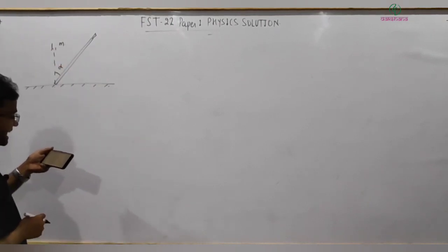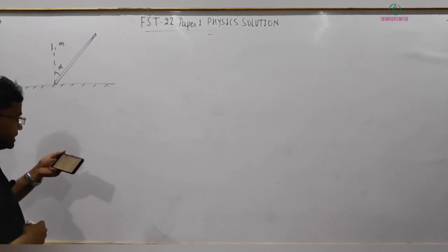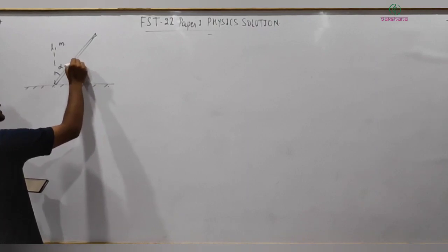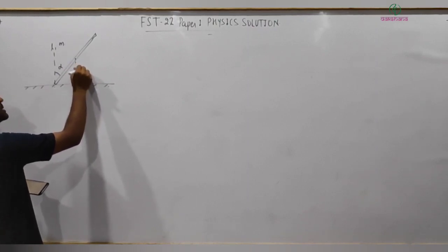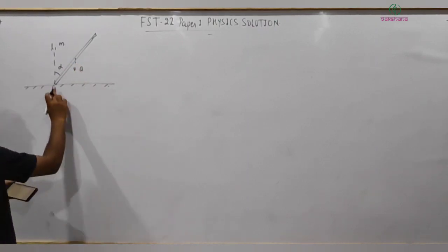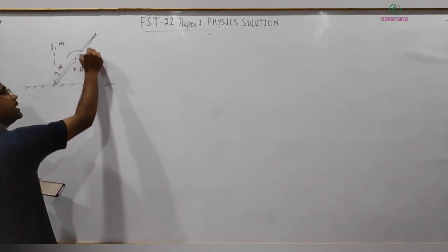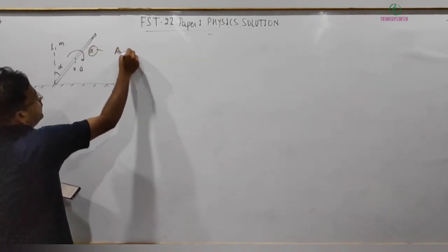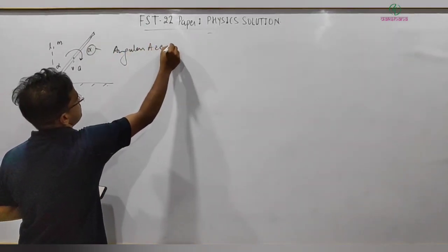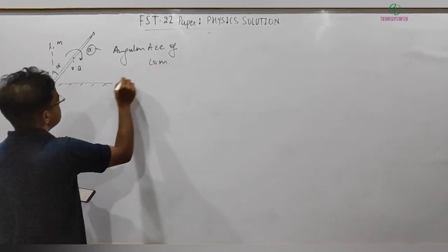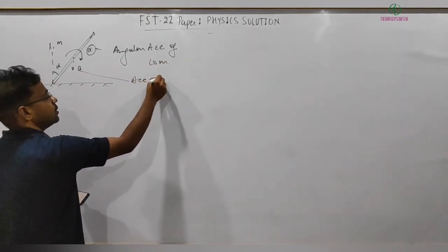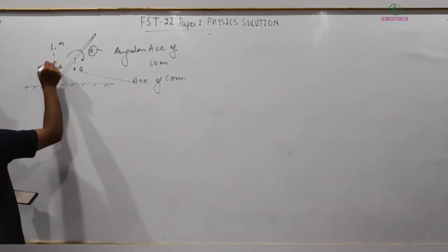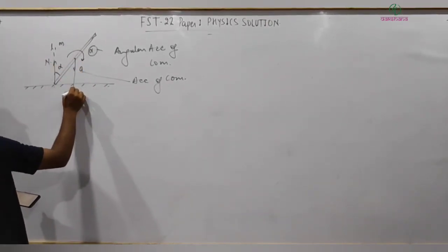The rod makes an inelastic impact with the smooth ground, and just after the impact it is talking about the center of mass having some acceleration a, and after the impact it will also be rotating with some, let's say, angular acceleration alpha. a is the acceleration of the center of mass, right? And here, once it is striking, the normal direction force will be there, and mg.